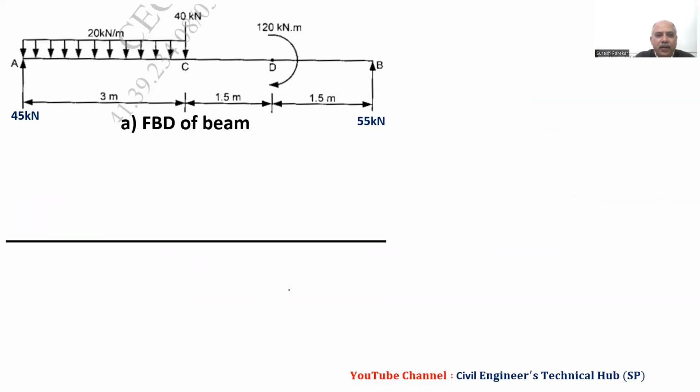Then we will go to the bending moment. We have the bending moment diagram. We will have to start again from the left, and we have 0 at the supports, at concentrated loads, at the start and end of the UDL, and at the left and right of the couple. At A we have 0.